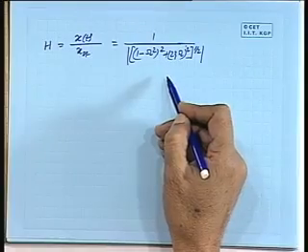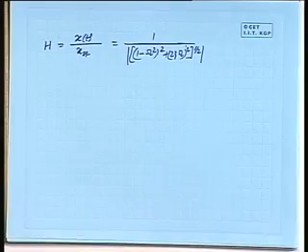So, if you have a structure with 0.1 as the damping ratio, you get 1 by 0.2, and 1 by 0.2 is 5 times the displacement. So, it is not blowing up to infinity, but to 5 times, 10 times, 20 times maybe, depending on the damping ratio in the structure you have. So, what we normally see is that it just vibrates and then it calms down. Is that clear?